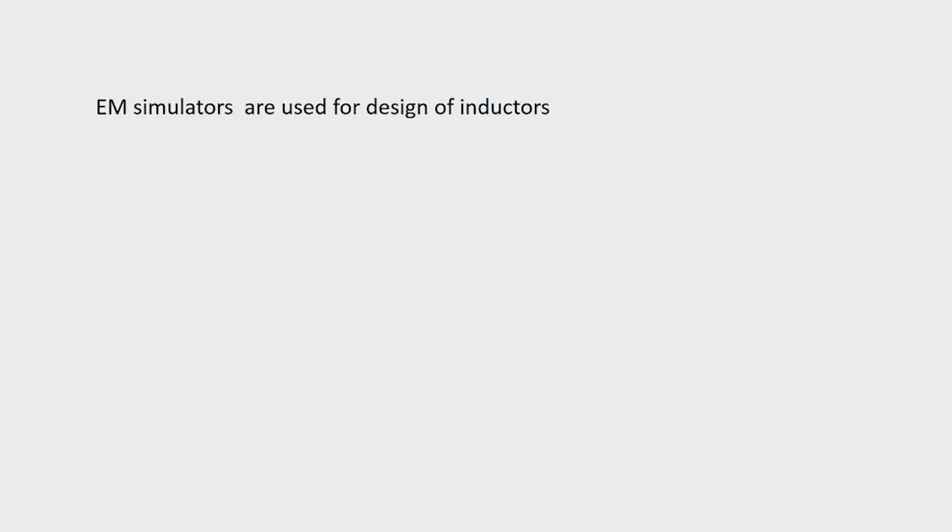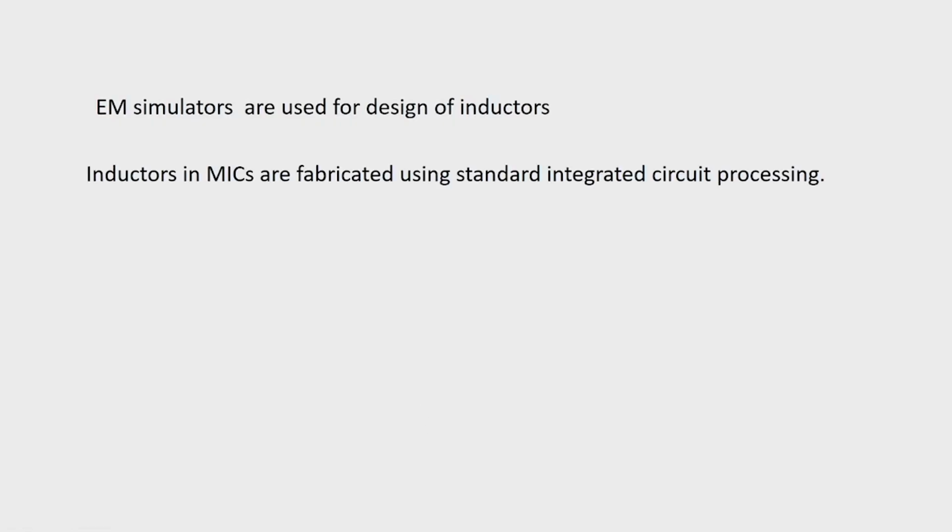Of course, many parasitic elements also need to be considered while making the calculation. For example, we can have an interturn capacitance. Usually EM simulators are used for design of inductors, and inductors in MICs are fabricated using standard integrated circuit processing.